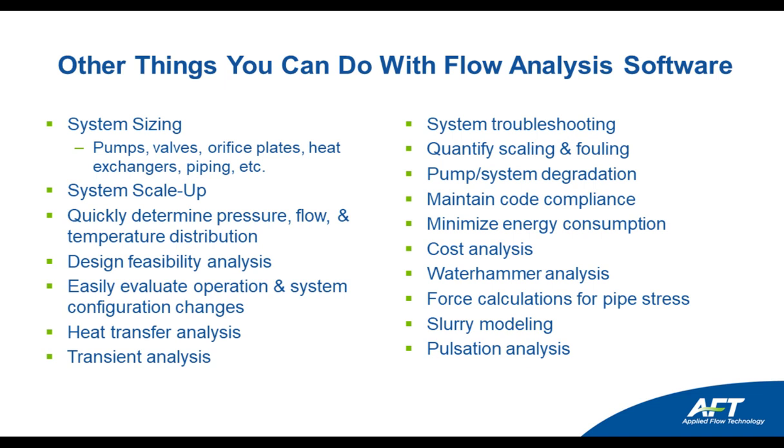It's important to maintain code compliance, and so software can help highlight where your maximum or minimum pressures or velocities for your requirements would be violated. It's helpful for finding ways to minimize energy consumption. You do full cost analysis. Water hammer analysis is really important to ensure the safety of your system. You can do force calculations for pipe stress analysis, slurry modeling, pulsation. There's a lot that you can do with a good flow analysis tool for your system.